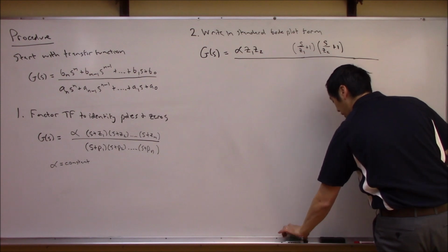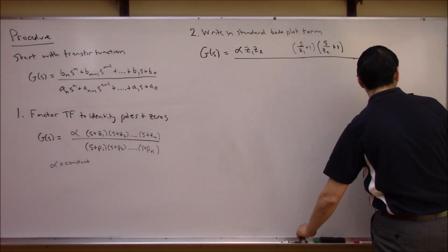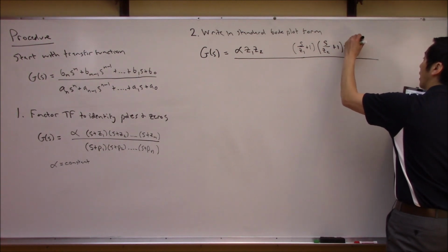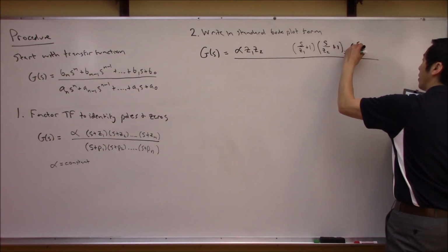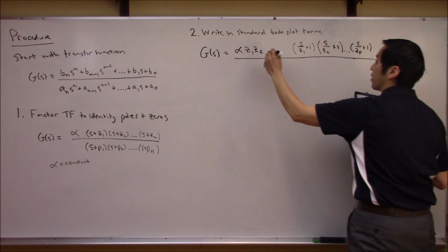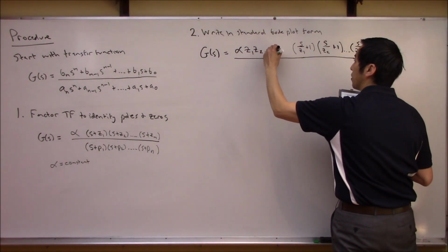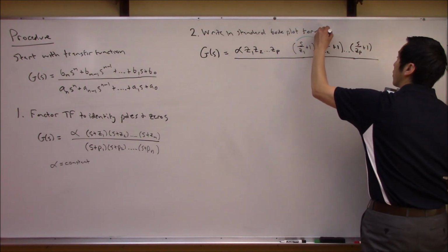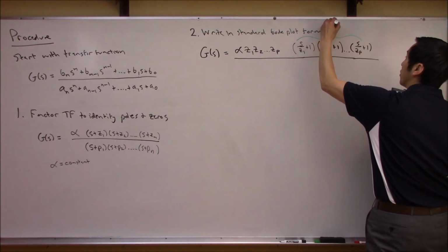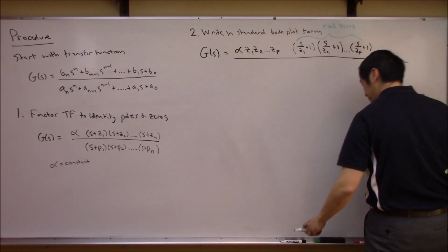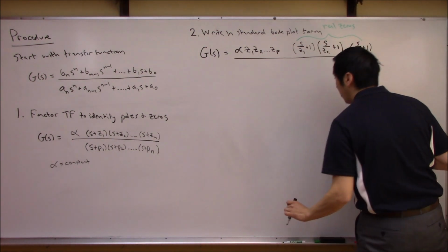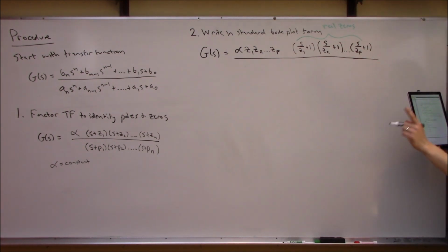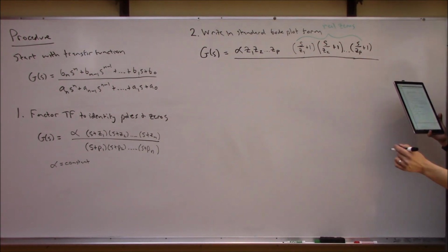So maybe what we should do here is keep on doing this all the way down to s over z(p+1), and then you get this zp, right? So these here you can think of as your real zeros. Now, if you had any complex conjugate pairs of zeros, if you remember from our previous video, we also discussed what that looked like in standard Bode plot form.